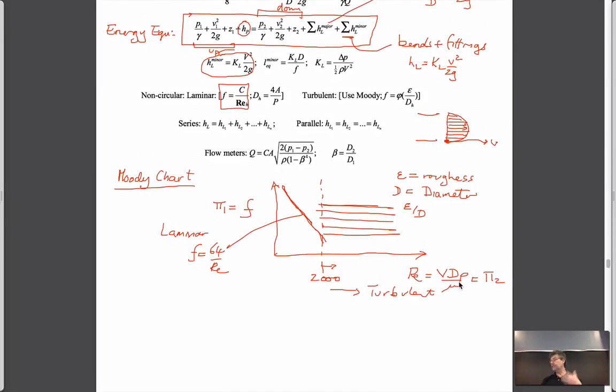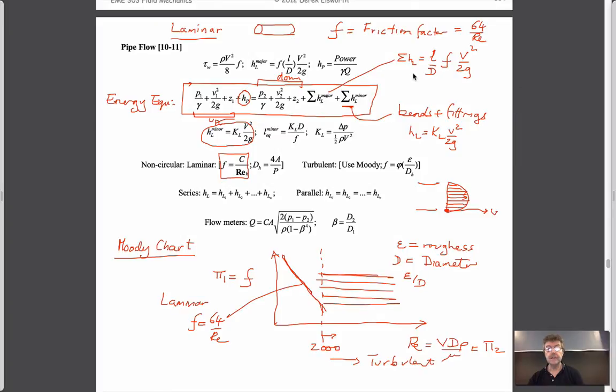We've shown through our very simple use of this flow equation for pipe flow that the magnitude of this major head loss, it's a very small head loss, but it's major because it's over the whole piping system. So if you have 3,000 kilometers of pipe going from the Gulf up to the northeast, then it's a very small loss per unit length of the pipe, but over 3,000 kilometers, it's a big number that you have to overcome with a pumping power in the system. And so we could rationalize the fact that it's a function of v squared over 2g.